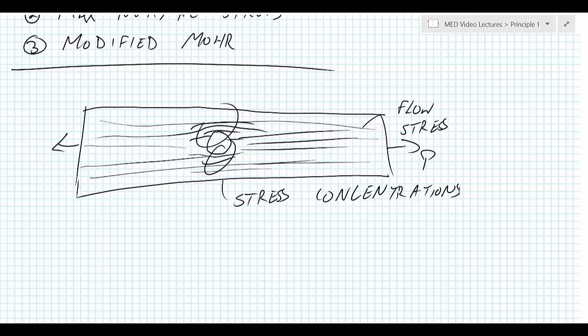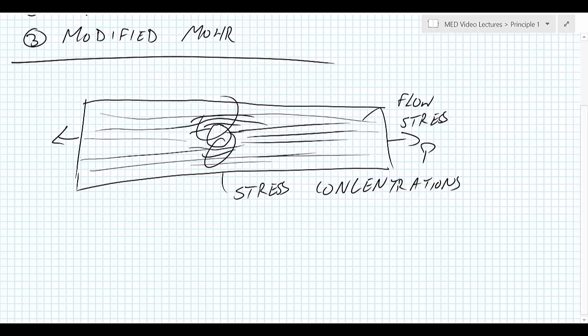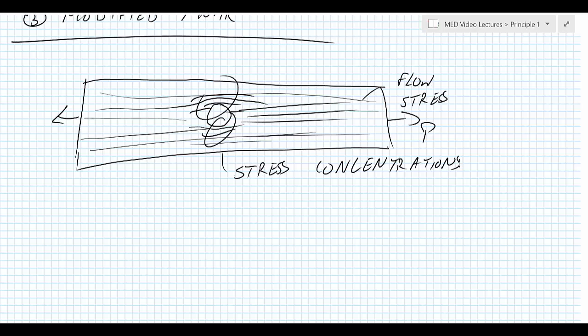When we look at brittle failure, it's going to be really important because when something fails brittly, what we mean is that a crack grows very quickly. If a part is failing ductilely, we're going to find that the static failure doesn't make much of a difference. The stress concentration doesn't make much of a difference. But when we are talking about fatigue loading, which is, again, crack growth, these stress concentration factors are once again going to become important. Stress concentration factors are very simple to use.